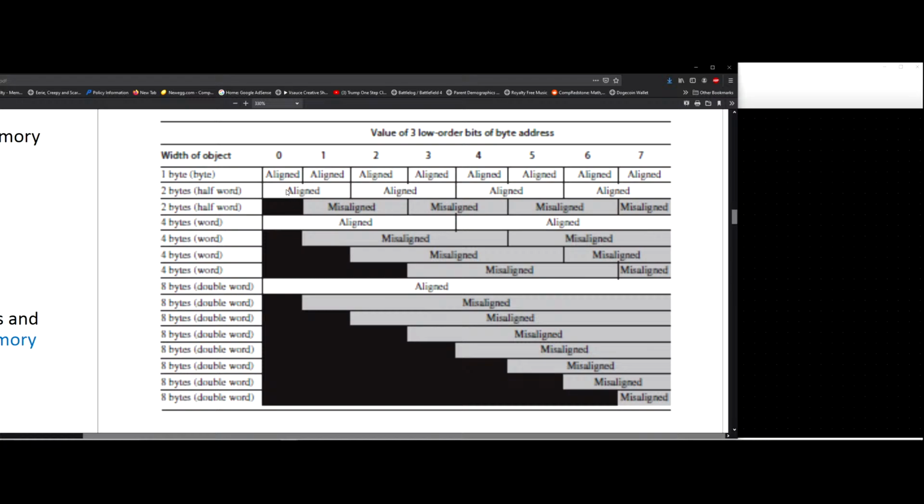So when you're doing byte addressing, if you have byte addressable RAM, you can read and write a byte anywhere. On halves, they can only be aligned on the 0th bit being 0, and on words, they can only be aligned on the 2 bottom bits being 0. So that's going to be our condition on how we're going to generate this memory. And then, of course, they show 3 because then you can go past 32 bits with 64-bit systems.